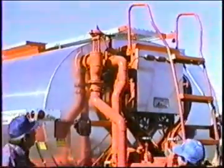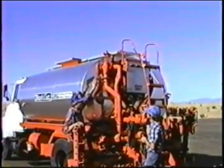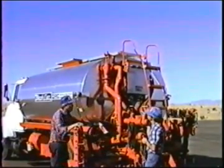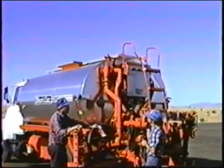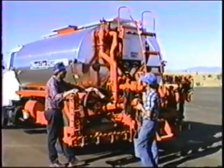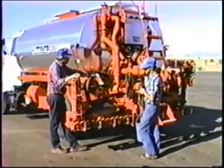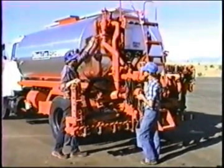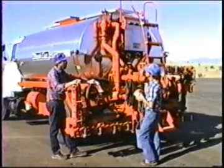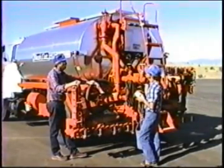isn't right. Also, at the end of the spray bar and at the end of the spreading system is the air relief valve. If for some reason that relief valve didn't close, well, it would let material leak back into the tank, and again, our spread rate wouldn't be right. If we've metered it with the pump, then it has to go out on the ground in order for our rate to be as we have set it up. And of course, the only way that this would be a problem is if we had some mechanical malfunction, but that is one of the first things to have in mind. If the spread rate is coming up light, you need to determine if that relief valve is functioning as it should.